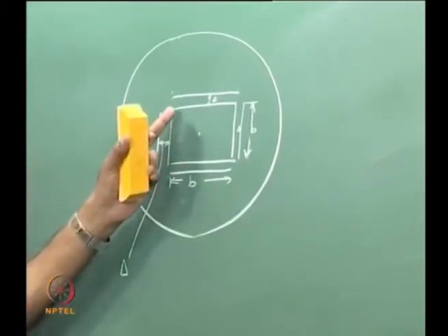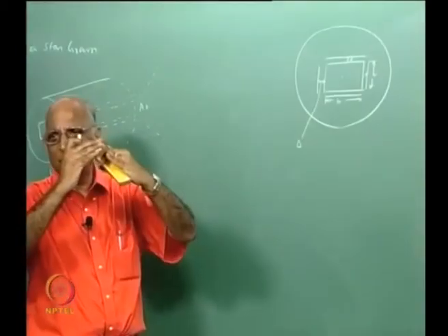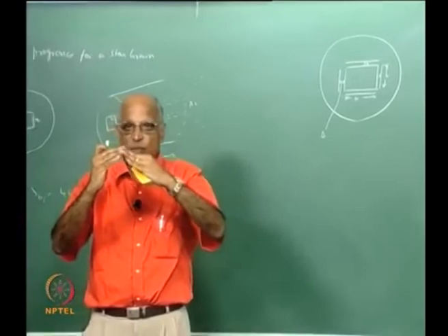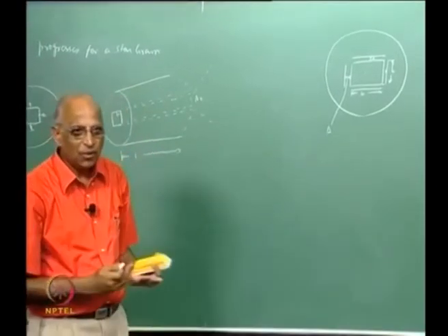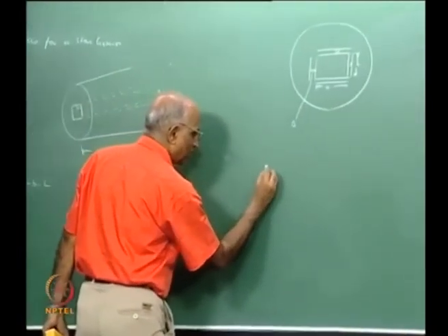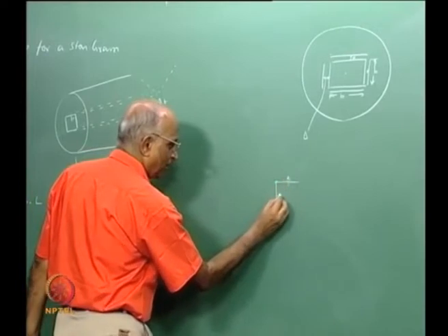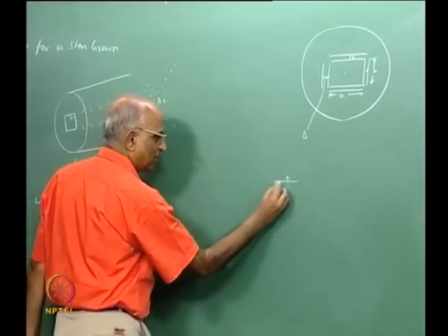How do the points evolve? How does the vertex of the two lines evolve? We said burning is always normal, therefore how should it evolve? Let us say I have this vertex here, burning surface is normal here, burning surface is normal here, this is the surface which burns.